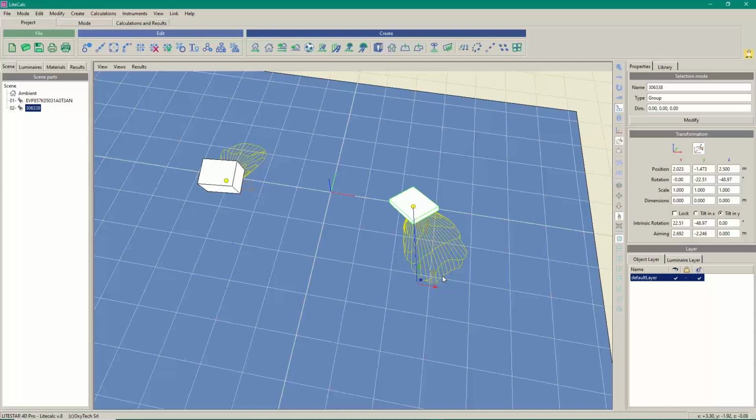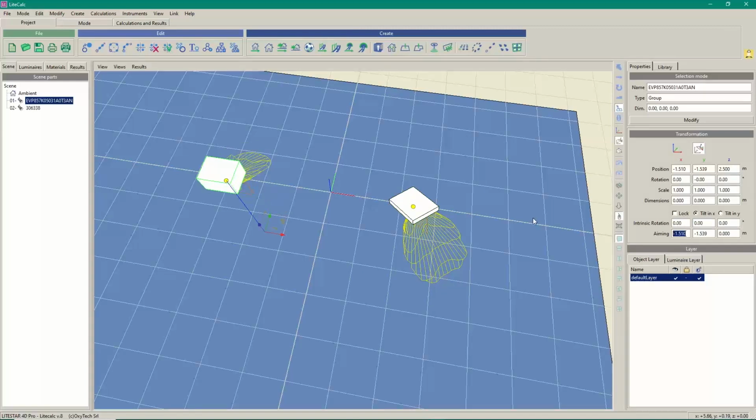So if you want to manage the high mast and put the luminaires over there, you have to first consider how the measuring system was linked to the luminaire. And in function of that, if the program is not able to recognize the tilting, then you have to do it by yourself. So for example, if we consider this one and we put it down at 0, 0, 0, it's perfectly horizontal, and we copy it.